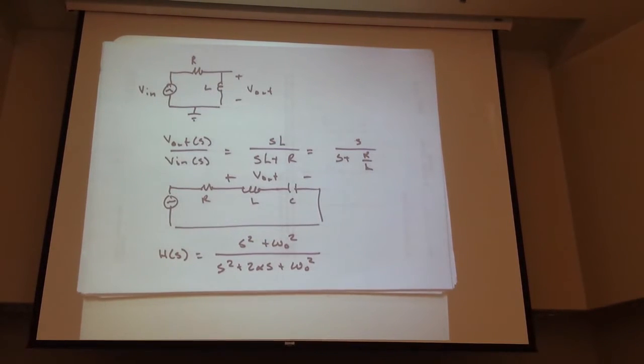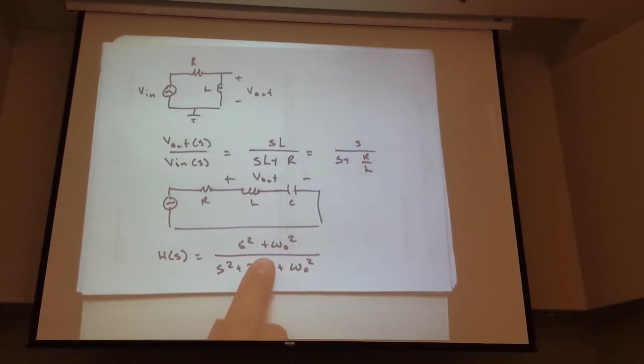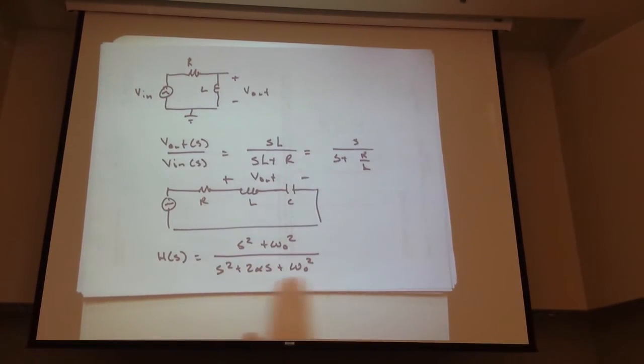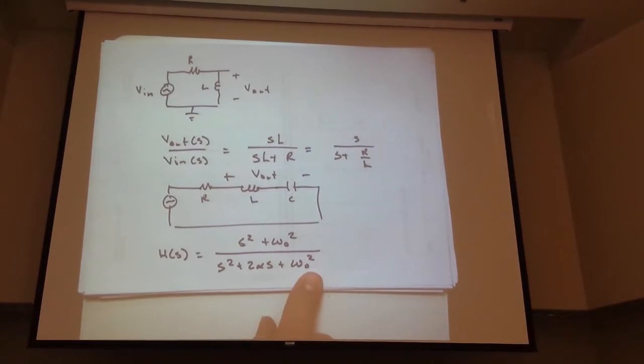That's what the transfer function is. There's a double 0 now at plus or minus j omega naught, effectively. And so, do we worry about designing for this? No, it's an artifact of the measurement. You design for the two poles that are in the denominator here.